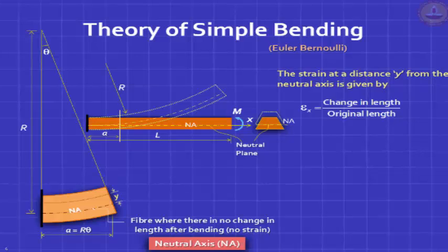So transversely, it's at a height y, and longitudinally, also we are saying it's at a location a along the x-axis. You will find that in a case of pure bending, it doesn't matter where that x is. The distance a doesn't matter because you'll find this bending moment is constant everywhere.